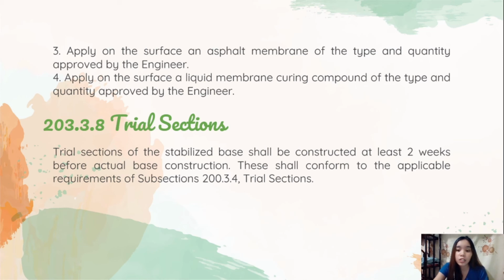So maintenance shall include immediate repairs of any defects that may occur before and after the lime stabilized base course has been compacted and finished. This work shall be done by the contractor at his own expense and repeated as may be necessary to keep the base continuously intact. So, kailangan yung proper maintenance.